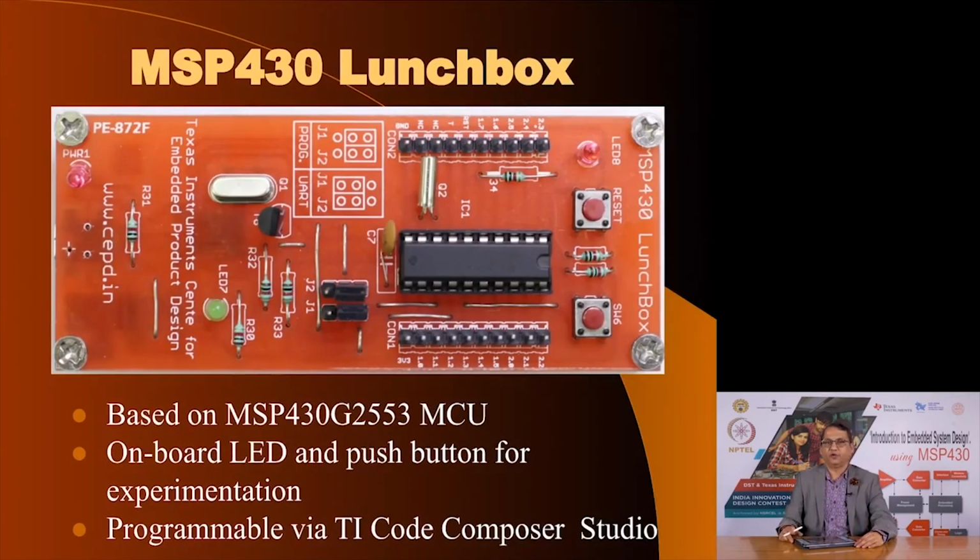Here is the photograph of the MSP430 lunchbox, and let me show you. This is the microcontroller MSP430 G2553. Here is the reset switch, here is the user switch. We have the power on LED here, and a power on LED is very important component to have whether you are designing an evaluation kit or your own instrument, because that is the only way to convey to the user that the power to the system is on.